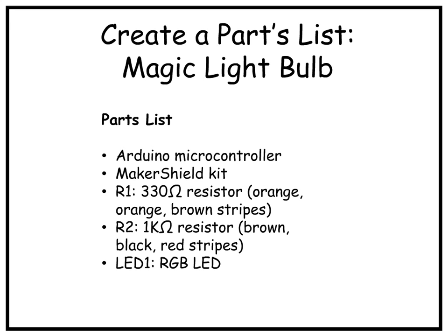Okay. Now there's two resistors here, and we talked about what a resistor does. It's basically there to just slow down the little excited electrons that are flowing from the power source, meaning in this case a 5-volt power supply that's on the Arduino board. Well, resistors have these little stripes, and there's a color code that's associated with it. Now, if you venture into electrical engineering, one of the things you have to learn is how to read that resistor color code. So what I did was, again, not getting into that nitty-gritty world of electrical engineering, I put the color code for you. So when you look for these resistors, all you've got to do is just look for the stripes there. So this 330 ohm resistor, and that symbol right there looks like a horseshoe. That's ohms. It's omega, but we use the word ohms because that's the unit for resistance.